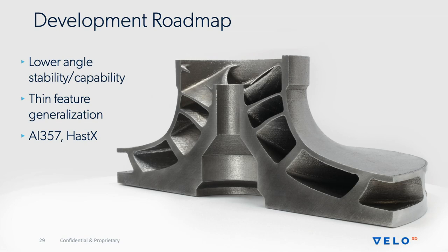Now that we've gotten into nickel-based, titanium-based, and aluminum-based alloys, it's relatively easy to expand in those metal bases. And one important note about these improvements is that these are simple print preparation software upgrades because they're just process changes. They're changes of the laser commands. So it means that you don't need to upgrade any of the hardware on the system. The system doesn't run differently. There's not a next generation system that you have to buy to get this technology. And all this license is included with the purchase of the system.